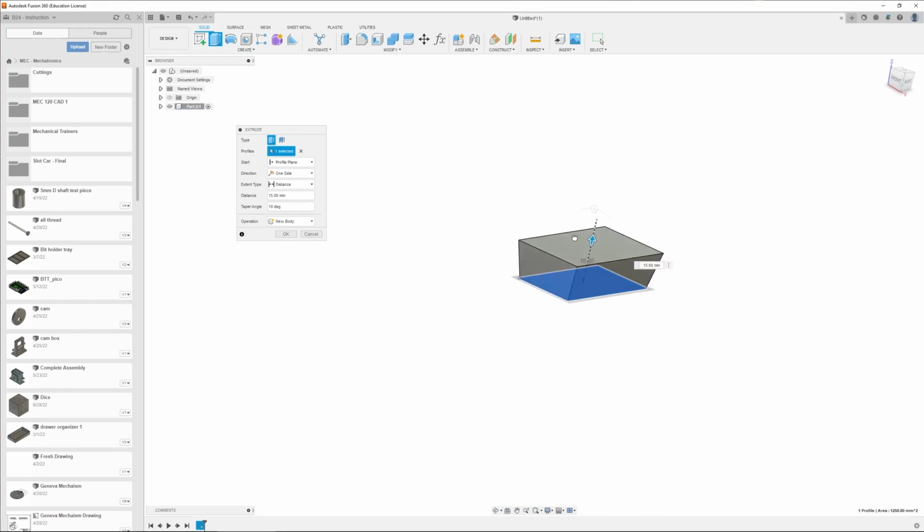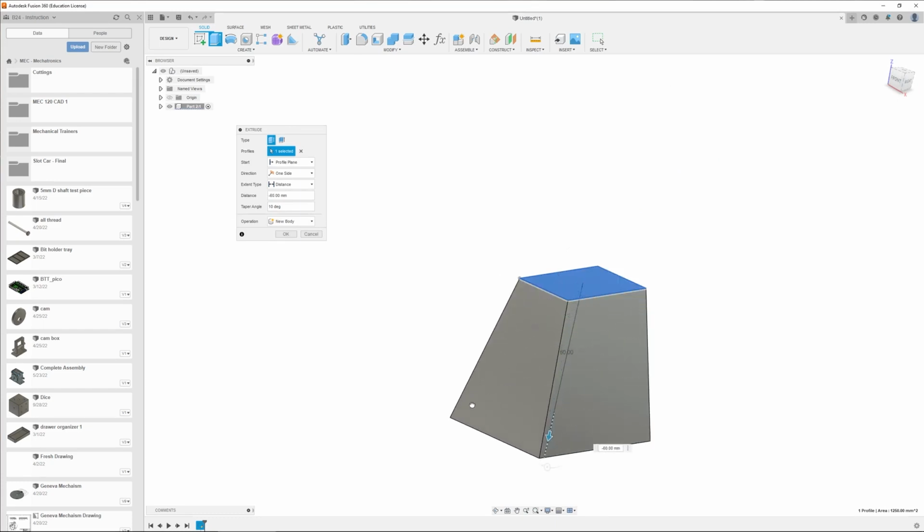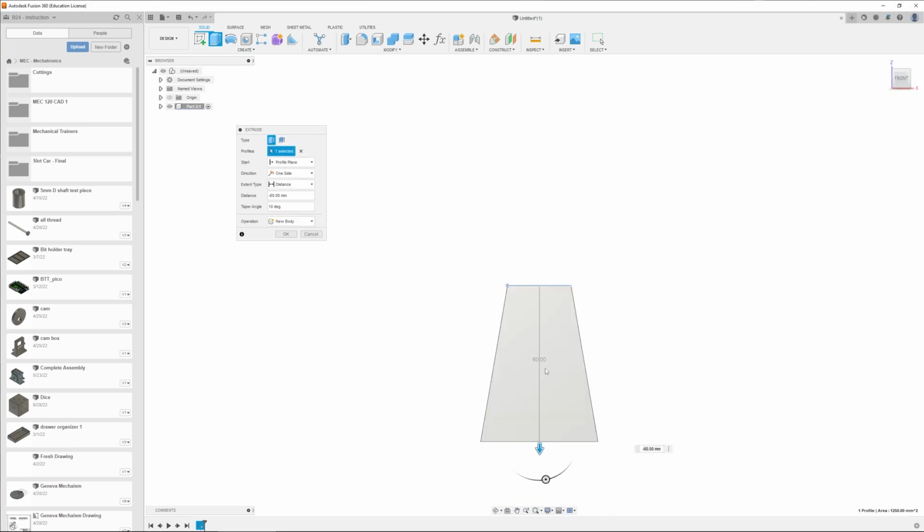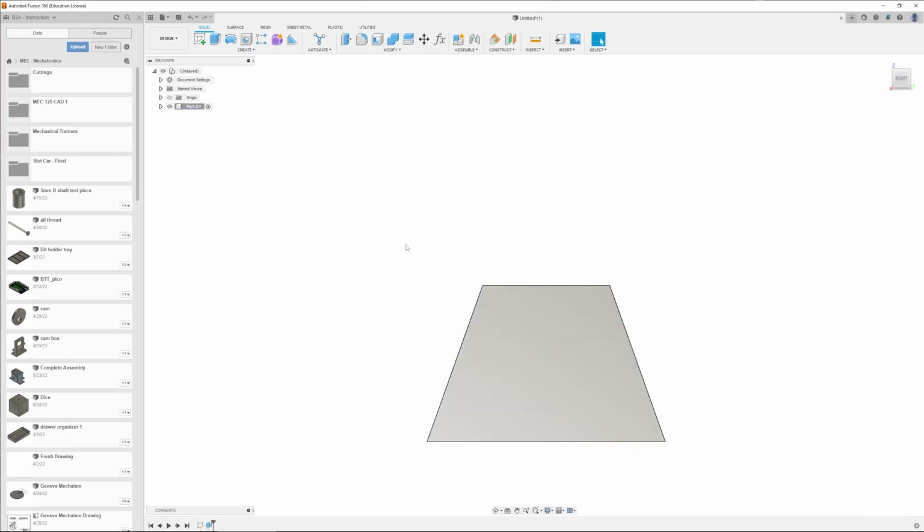That's in the positive extrusion direction. If we move in the negative extrusion direction, from the same orientation of the camera, we start creating something that is more pyramid-like. And if I rotate in the opposite direction, you can see that we have this taper here. And we can make this taper more acute. Since I accidentally entered that value, now would be a good time to demonstrate one of the features of the timeline.